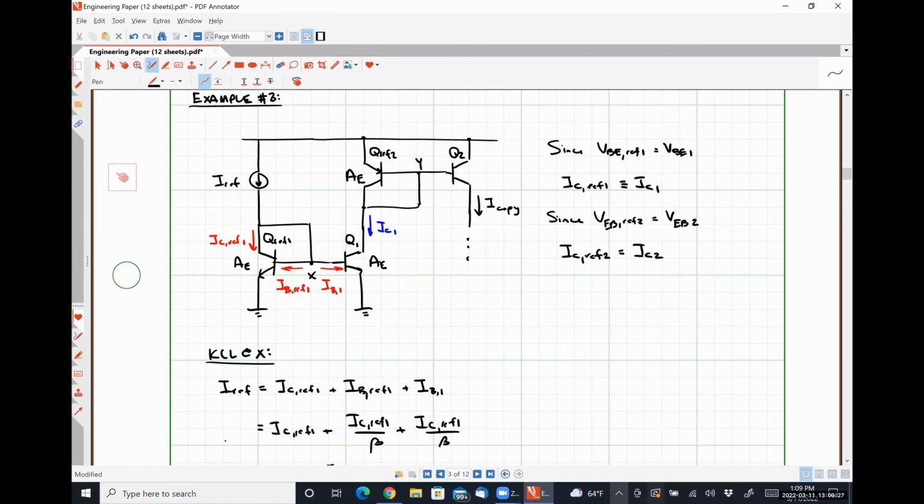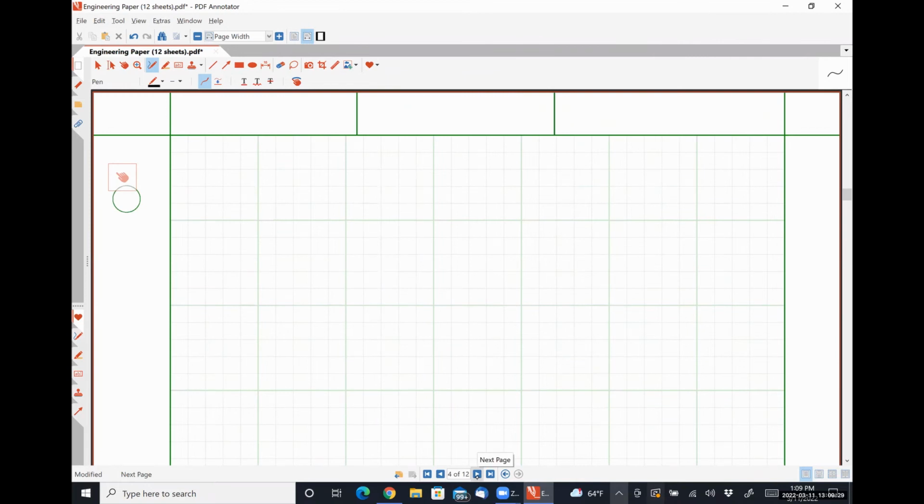All right. So our last topic for the day will be MOSFET current mirrors. This is going to go pretty quickly because, as Mr. Boyle pointed out, there is no opportunity to steal current through the gate. Yeah. Oh, no, there's not no error. It's just not error from that. The error comes from channel length modulation. It's not as bad.